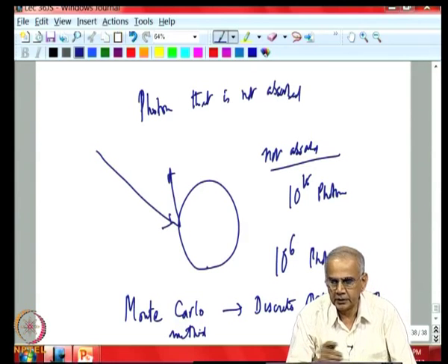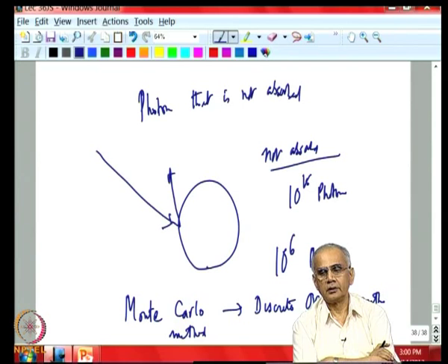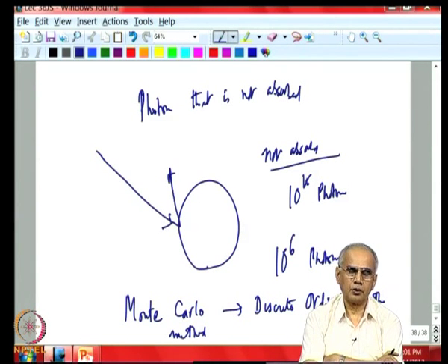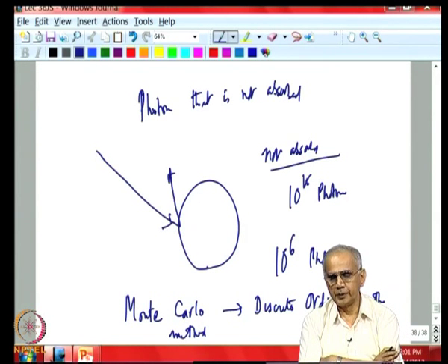So, many examples are done in the literature for real life examples like boilers, glass tank furnaces, and such examples, they all demonstrate that in real life complex geometries that you encounter in engineering applications, Monte Carlo is generally superior to all the other techniques discussed in these lectures, that is discrete ordinate, exponential kernel approximation, maybe a finite volume method.